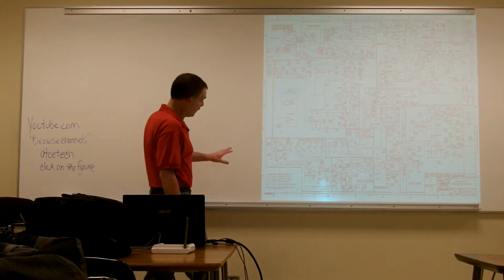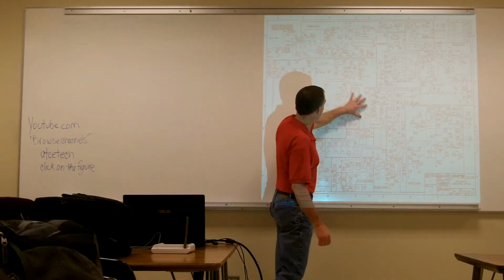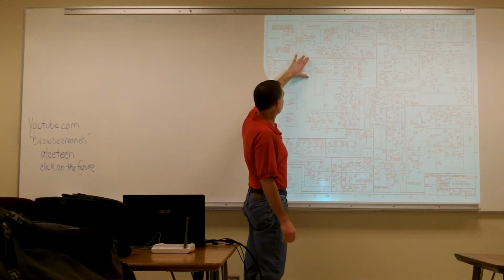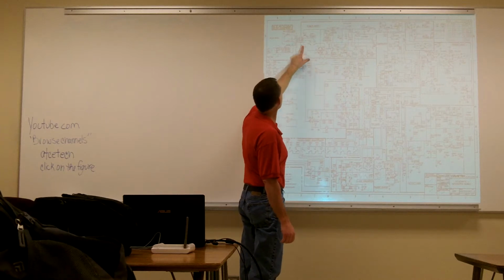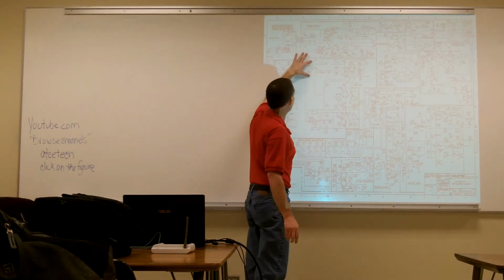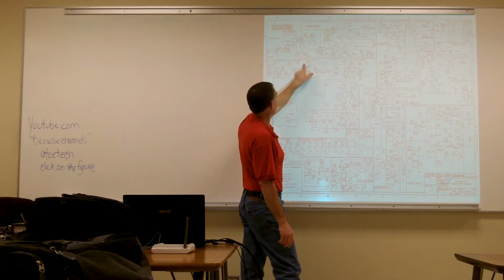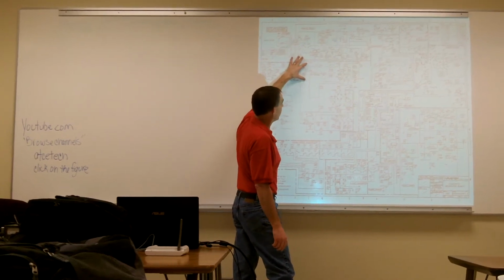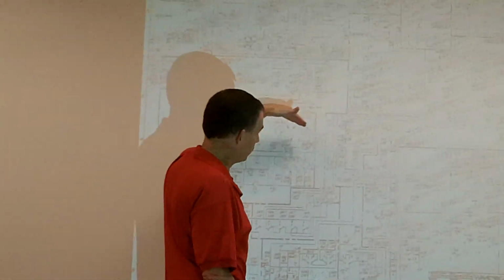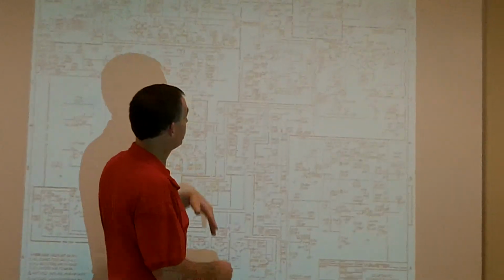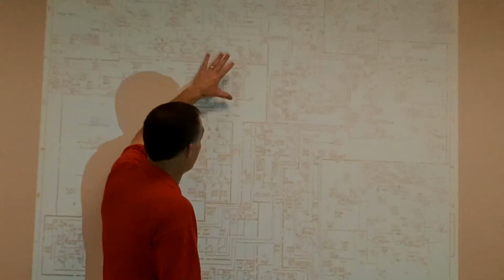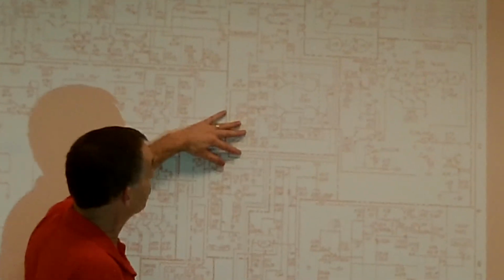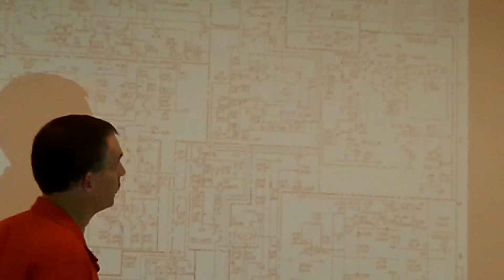So depending on what type of power supply you have is depending on what the output impedance of that supply is. But we're going to start going over this schematic next week, because there are certain things that we can already start identifying. For example, on top of C7, here's the grid, C7, we have a voltage divider, and then we're using a potentiometer to vary the voltage going into that voltage divider. We can start identifying a lot of circuits that we're already starting to use, especially the voltage dividers. You can look all over the place. Anytime you see two or more resistors together, those are all going to be our voltage dividers, and those are reference signals going into our other circuits.